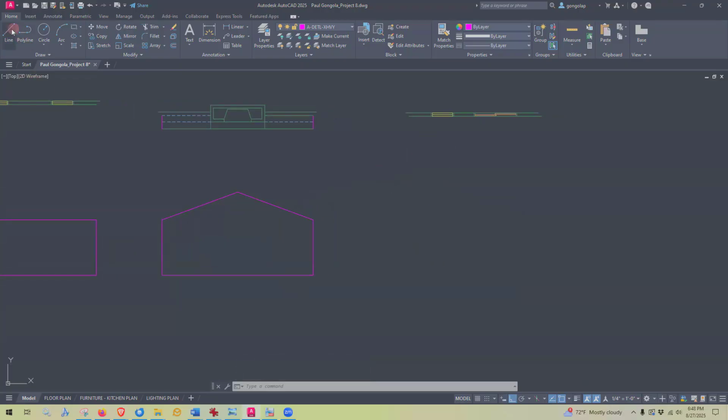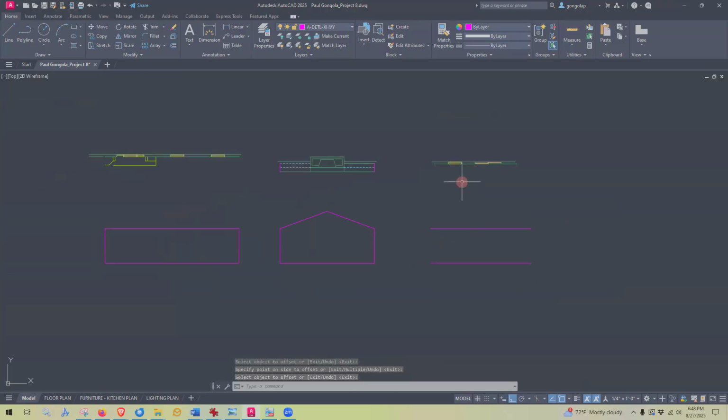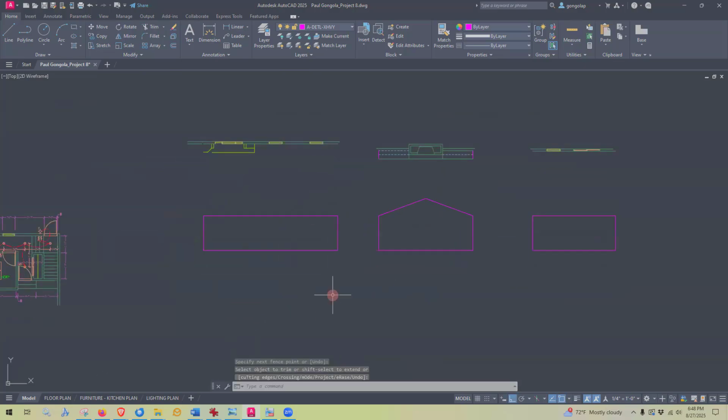Okay, so let's just quickly do the third one. And again, I'm going to go with my line tool, and I want these all to line up. So I'll just start here, and I'm just going to O track over, and then left click and draw that floor. I'll offset 8 feet. I'm going to do this one just a little quicker because I think you got the gist of it. And then I'm going to do my trimming. And I've got my 3 rectangles. Lovely.